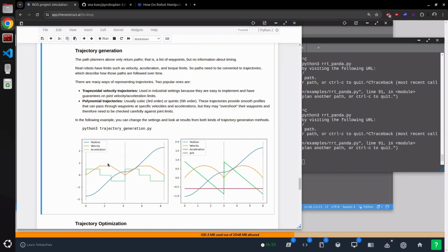Polynomial trajectories, on the other hand, have more smoothness properties. Depending on higher orders of the polynomials, you can get away with discontinuous accelerations or discontinuous jerk. But you need to figure out exactly what the boundary conditions are. In both cases, really. Both the examples that you see here are doing a trajectory with two segments that is basically starting and stopping at 0 velocity, and that's how a lot of these work.